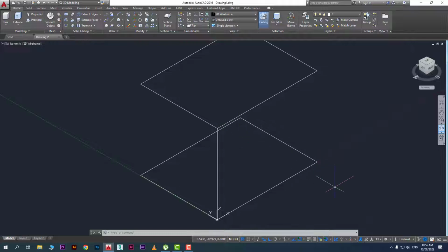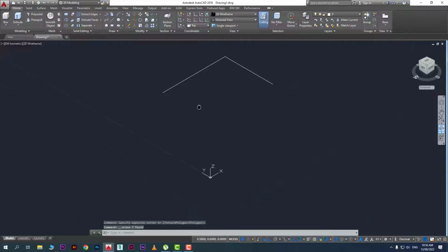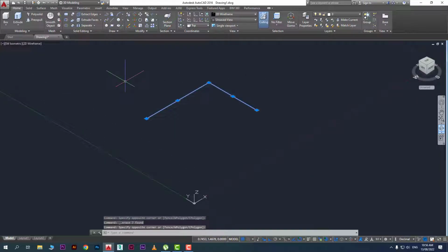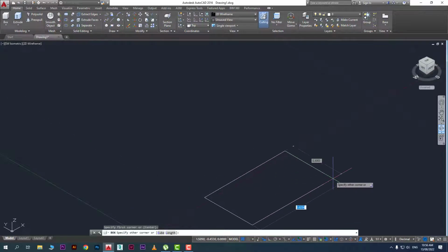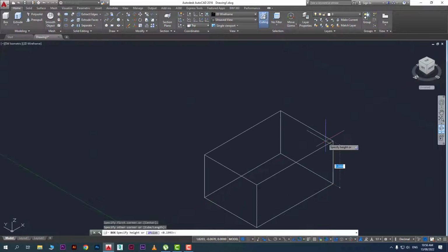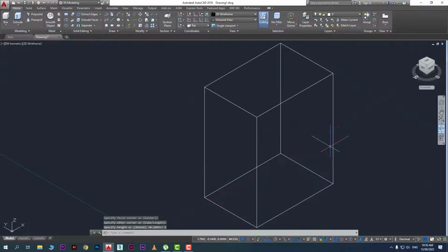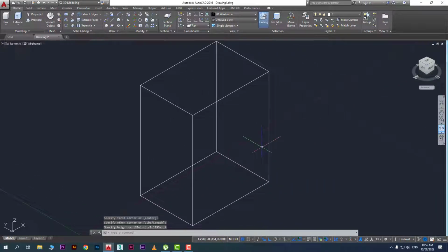All right. So what I will do next, I will select and delete all objects. Now it's time to draw 3D objects, all right, in 3D space. So I will draw first of all box from here, take box, all right, then just draw box from here. First it will ask you specify a first corner, okay, I will specify first corner, then the other corner, all right, then specify height. You can also specify height, like I want 1 unit, like any unit it could be, so like this. So we have specific width, then length, and then we have height as well.